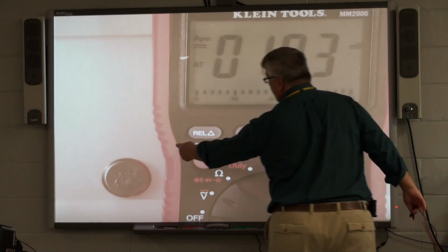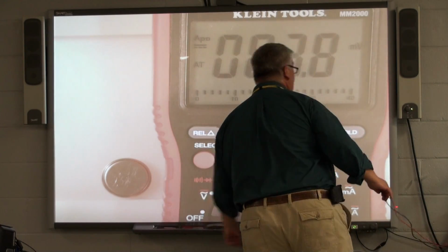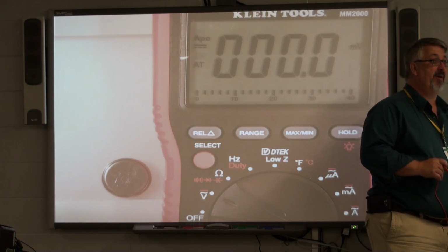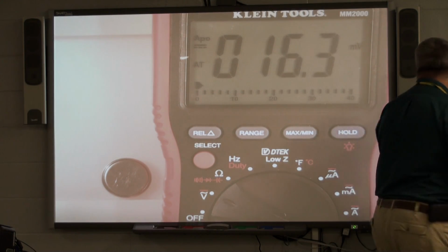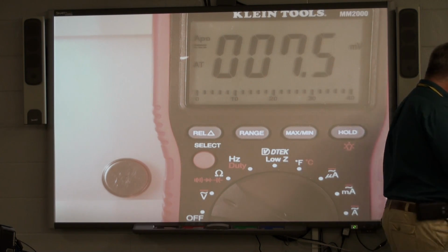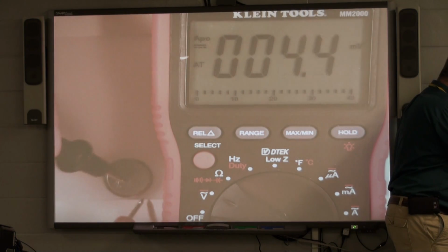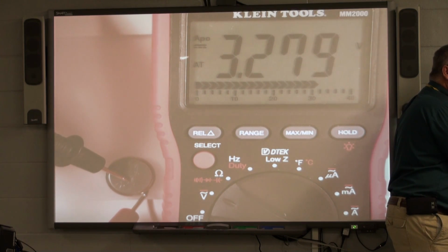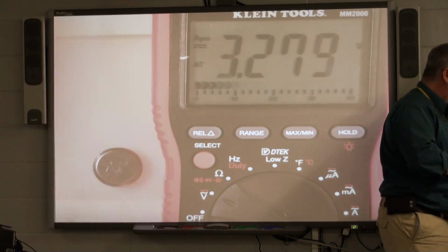And you'll see a little plastic separator that separates the two sides. So if I want to read this battery, the least awkward way to do it, let's see if we can still see the display. The bigger side is my positive, the smaller is my negative, and you see I'm reading 3.2 volts. Can y'all see that on the screen? Yeah. I can't turn around, or I'll let go of the leads.